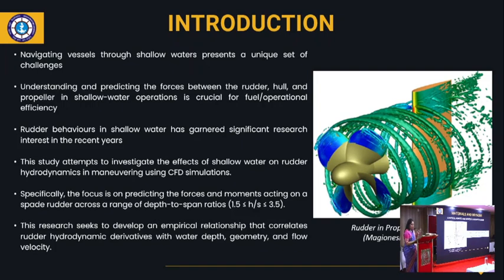If the rudder is going from amidships to the port, there is a net hydrodynamic pressure, because of the Bernoulli's equation balance, acting from the port to the starboard. So a net positive rudder force, a net positive rudder angle, but a net negative rudder moment, because the moment here is in the anti-clockwise direction.